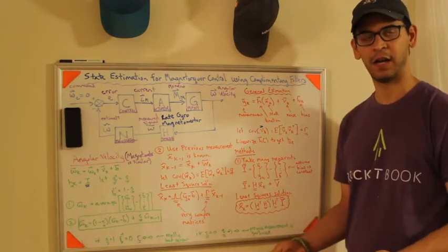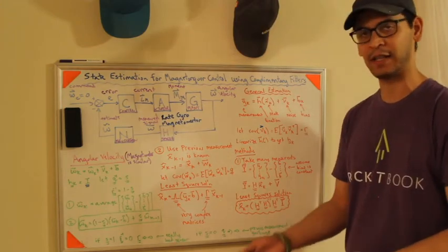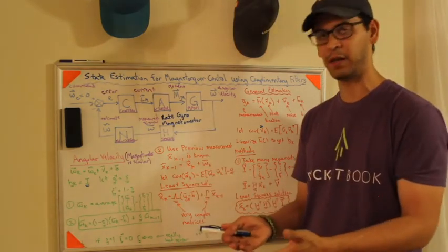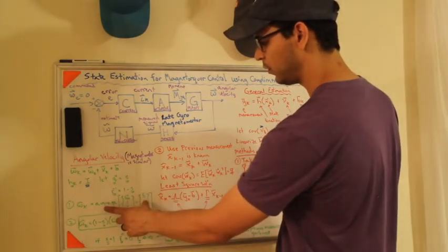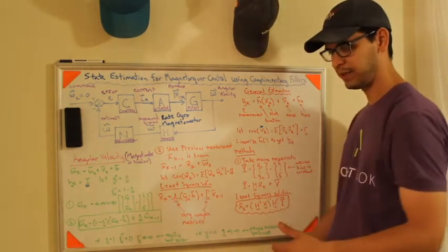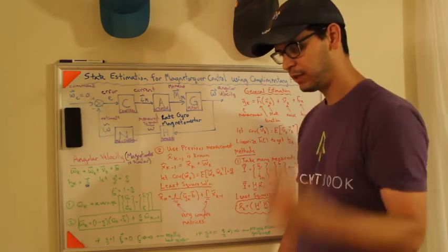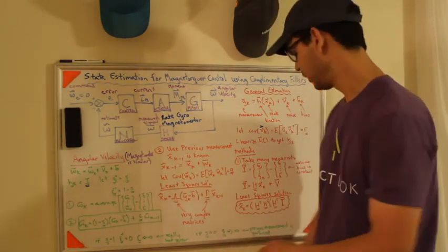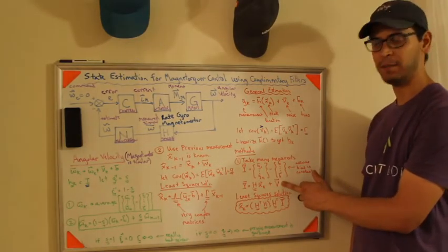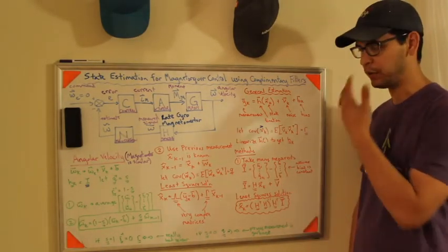And obviously that's the average. How do you take the average of a signal? You add up all of the measurements and divide by the total number of measurements. So if you use method 1, which is, say, every fraction of a second I take 100 measurements, if you just average them all together, you will filter out the noise. It may not be good, but you'll filter out the noise.